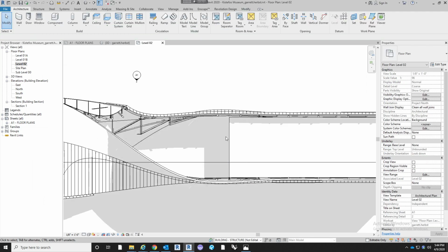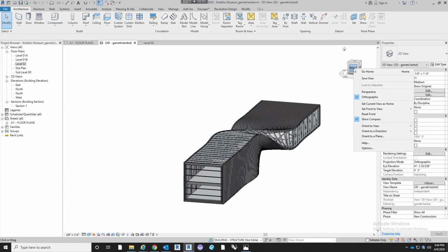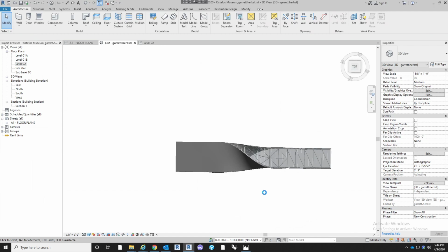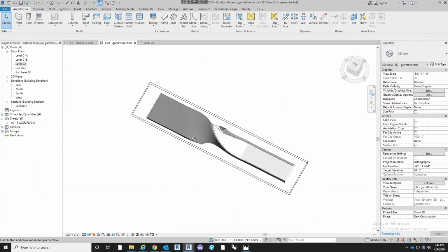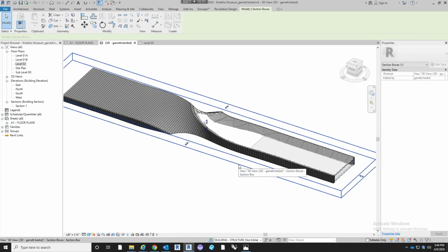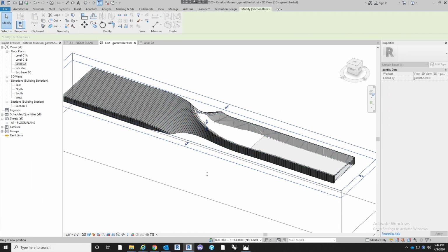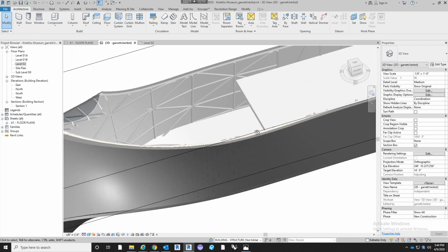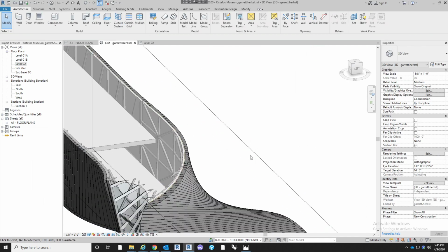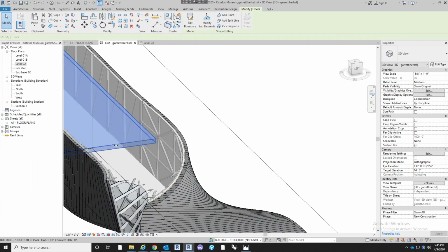All right, and so now if we go to 3D view, and we do that same shortcut where we right-click on the painting box, orient to a view, floor plans, do level 2. And that automatically generates at level 2. I'm going to take the bottom of the section box, drag it down. So that looks pretty close to the image. Probably a little bit thicker.